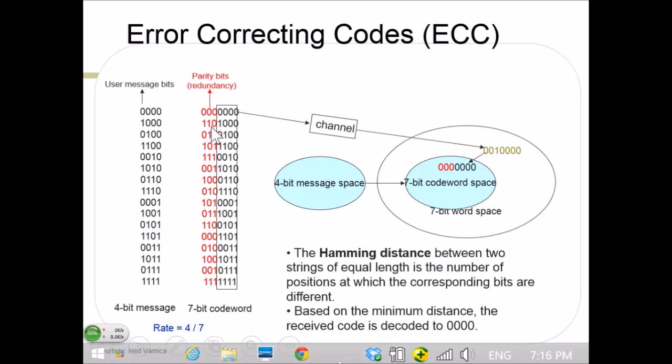If I transmit, for instance, the sequence 110100, then for that sequence to change to this one, there are 4 bit flips needed. So since only 1 bit should have been flipped otherwise, the probability of one bit getting flipped is much higher than all 4 bits getting flipped.